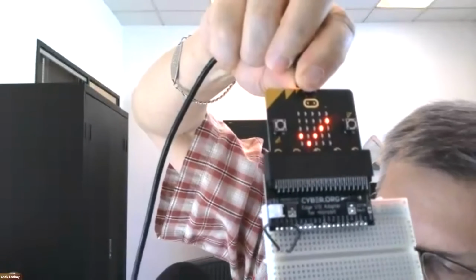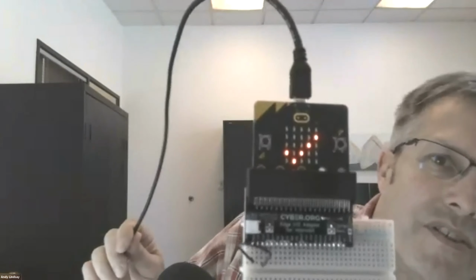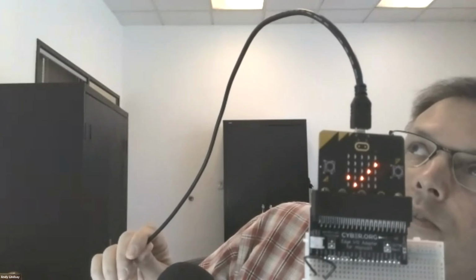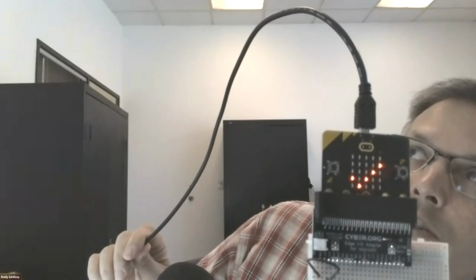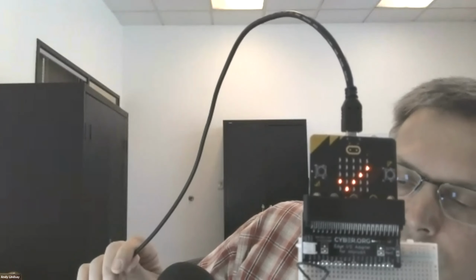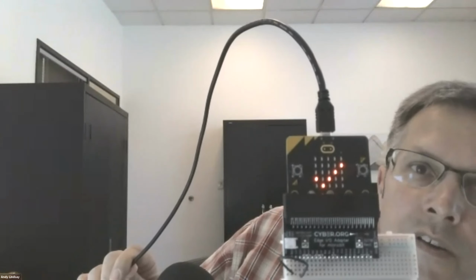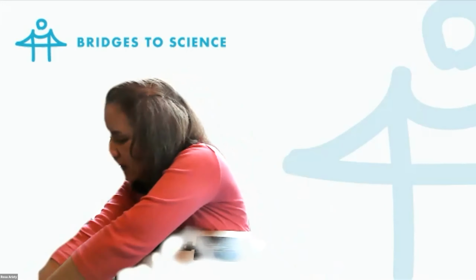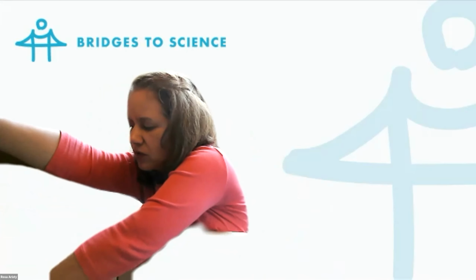Okay, good. So we know that something outside of your main system is responsible. I'm imagining possibly a bad solder job or connection inside one of the alligator clips. So let's try this again with just different colored alligator clips. I'll use the green and the yellow. We have lots of these at home.